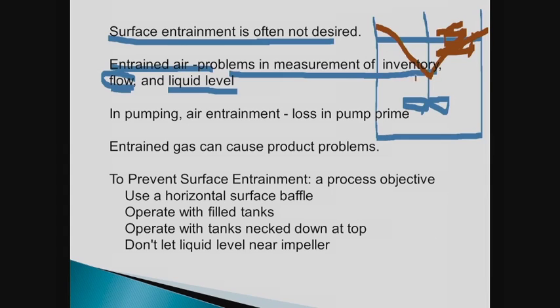What is the liquid level of a center vortex? And if you have foam, where does the foam end and liquid begin? So it's always interesting, that liquid level. Most people think it's not a problem, but it can be. In pumping, air entrainment could lose the prime of your pump. It's not uncommon for air entrainment to be so high that you lose your pump prime.